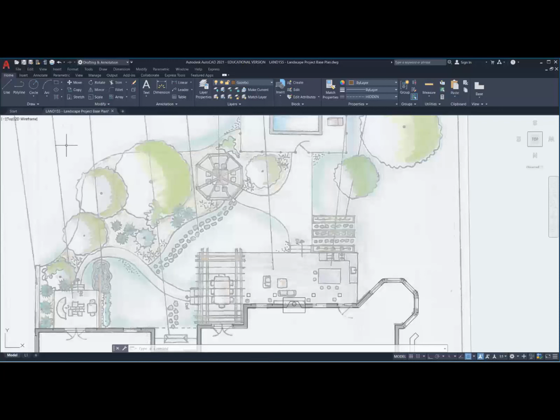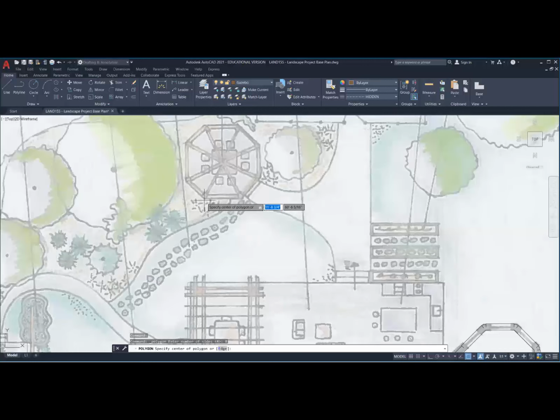This is an octagonal. So we have a command here under the rectangle command that allows us to create multi-sided polylines. So when I click on that, I have an option here of how many sides. This one has 8 sides. Okay. And then it says start point. So I want that to start at the edge, but before I pick that option, I want the option down below to make sure I'm using the edge command of the polygon, E and enter. It's asking me for the first point. So here's my first point.